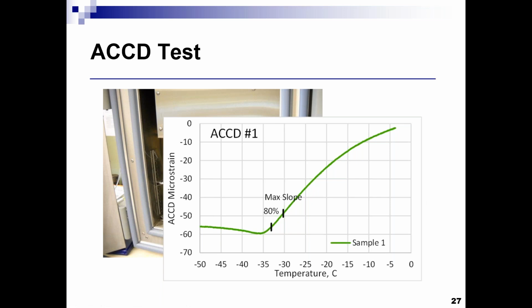Typically, softer asphalt binders like 58-28 will give you better low temperature performance than 64-22, and that's actually given from the name of the PG grade of the asphalt binder. When you hear 58-28, the -28 for the PG 58-28 is lower than the -22 for PG 64-22, so you would expect to get better low temperature resistance when using 58-28 asphalt binders.